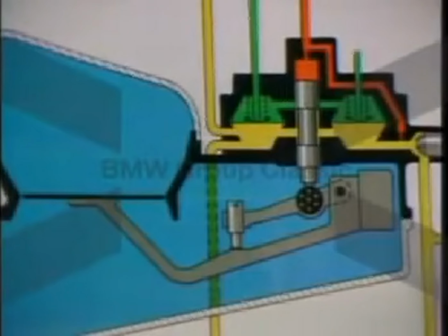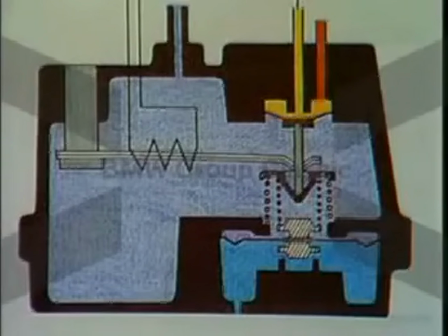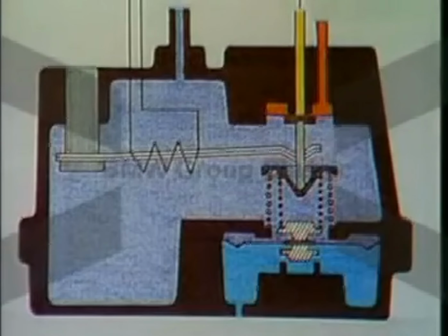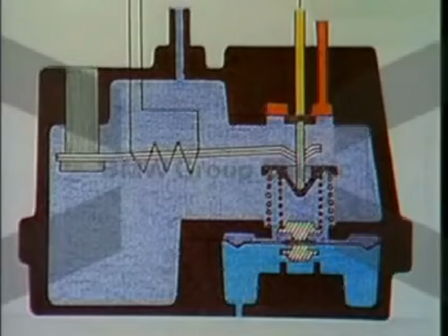In this way, it's possible, with the same quantity of air, for the sensor plate and control plunger to travel upwards further, allowing more fuel to flow through a consequently greater open section of the metering barrel slits to the injection valves. When the engine is warm, the bimetal strip function is inoperative. The control pressure is thus increased. A higher control pressure means less fuel.